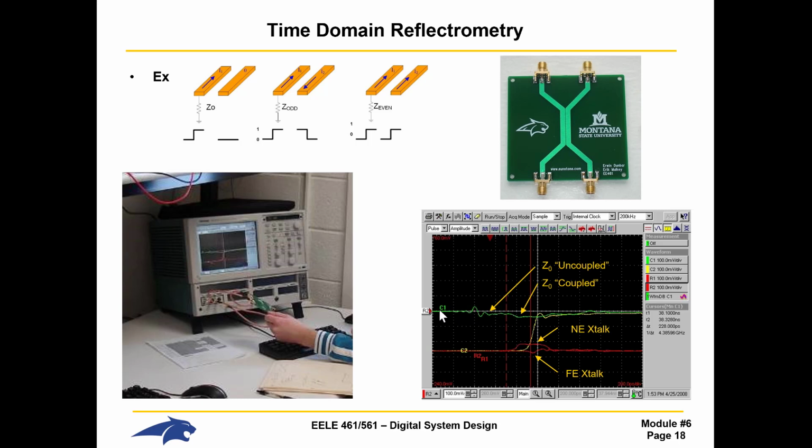It comes along, it's perfect 50, it's in the cable. All of a sudden, boop, boop, boop, all these bumps and wiggles. That is the reflections off of this connector. The connector has kind of an inductance to begin with, and it has this big capacitance as it gets onto the board and onto this plane. Then it's bouncing all over. And here's the 50 ohm trace right here. Notice that it's not perfect.